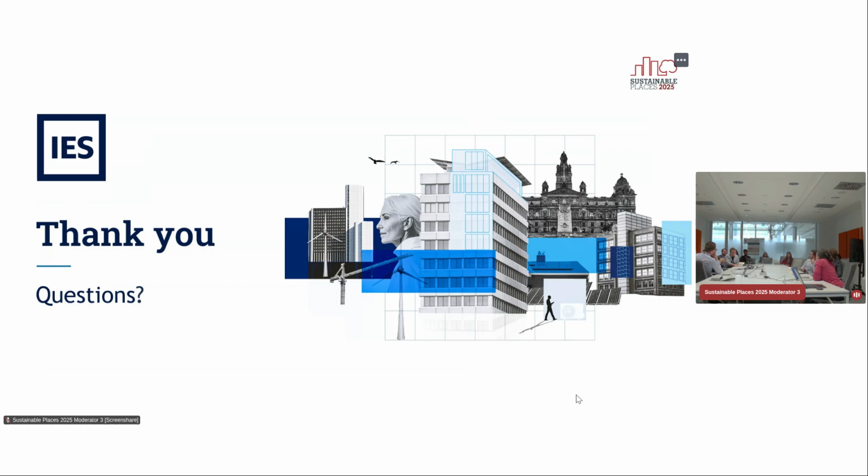When you establish the baseline energy simulation, for how long do you need to monitor a building, would you think? Do you need a full year data or ideally, typical seasons? I think it depends on what interventions you want to look into, right? So if you want to look at whole year seasonal, like heating or cooling savings, you're going to need at least 1 year measured data to compare against.